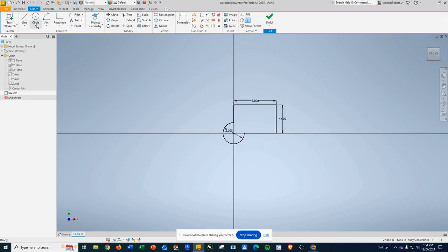So I am going to now use the line tool to create some shapes. I'm going to grab my line tool, click here and draw this way. And as you can see, I have a line length here, which I can type in as 4 inches, which will make a 4-inch line. And that's one of the times where, when you have an angled line, if you click this line afterwards, it really wants to dimension only in the vertical and horizontal distance.